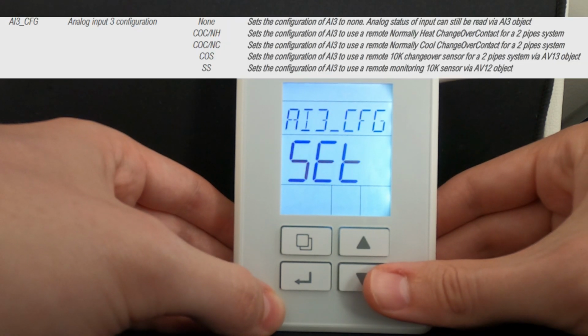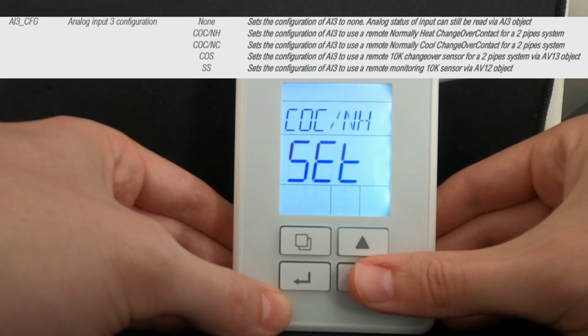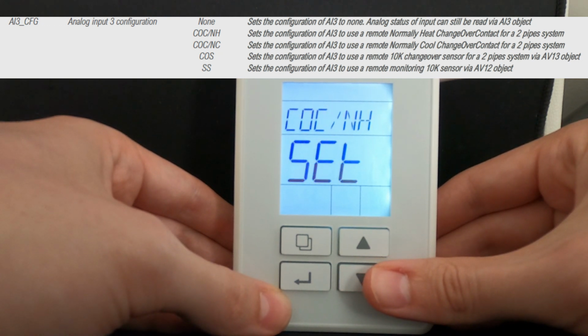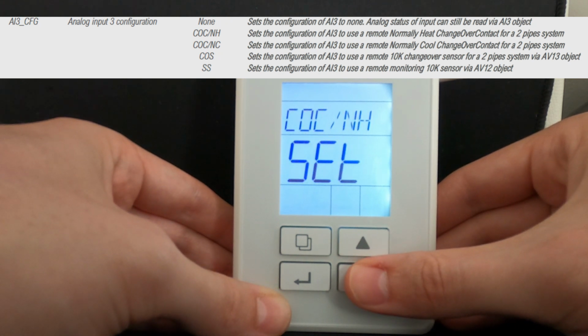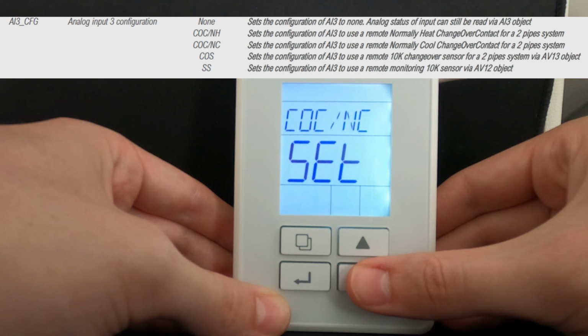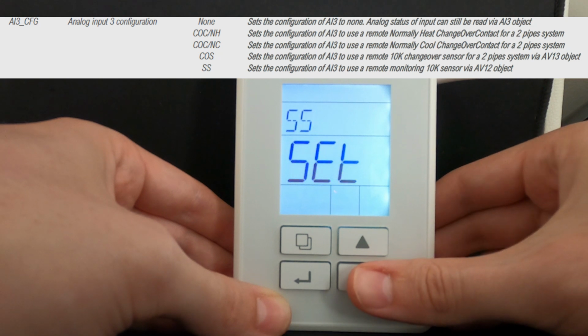Then for analog input 3, my options are none, changeover contact for 2-pipe for normally heat, changeover contact for normally cool, again for 2-pipe, my changeover sensor here for a 2-pipe system, and finally remote monitoring for supply.